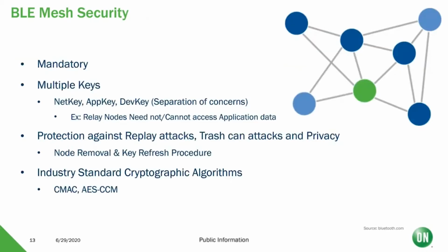Security. Security is an important concept within any sort of connected devices. Bluetooth Low Energy, BLE, was introduced, I believe, in the 2008 or 2009 time frame. Security was completely optional. It was left to the device manufacturer or the system integrator to figure out if they needed security. Everything was optional. There were hooks available. There was secure pairing available. All of those were available. But the BLE protocol itself did not mandate any security requirements.